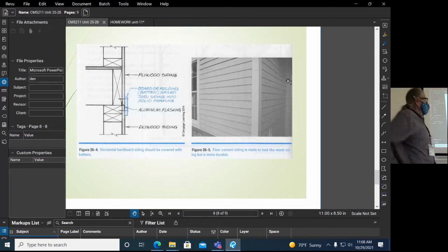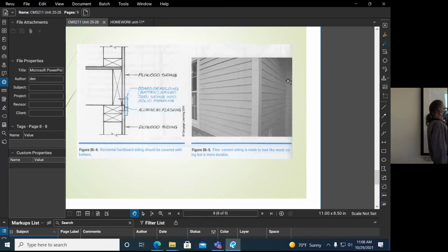Other types of siding include plastic, fiber cement, and aluminum siding. These kinds of siding attach onto the plywood and you flash them. The flashing keeps the water from entering into the system. There's also an exposure here, right? The siding is lapped on top of each other, similar to the wood siding. It could be aluminum siding where the pieces hook together.